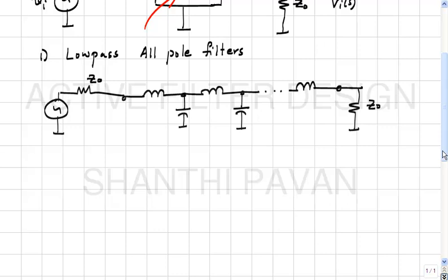If you have a passive electrical network, then any of the parameter matrices that you see, either the Y or the Z or the G or the H, the Z12 will be equal to the Z21, or the Y21 will be equal to Y12. Y11 will not be equal to Y22 unless the network is symmetric. Okay.